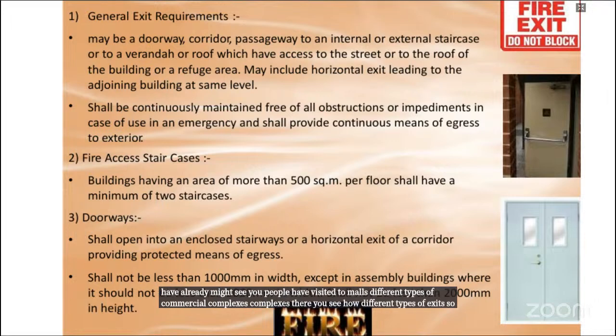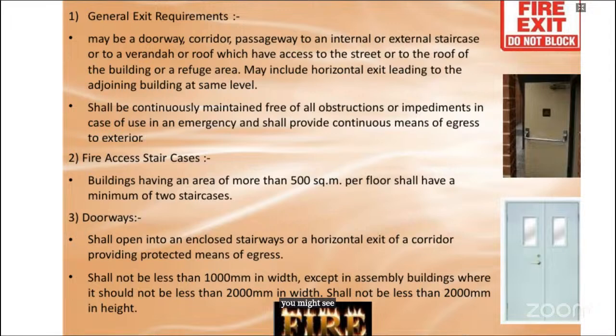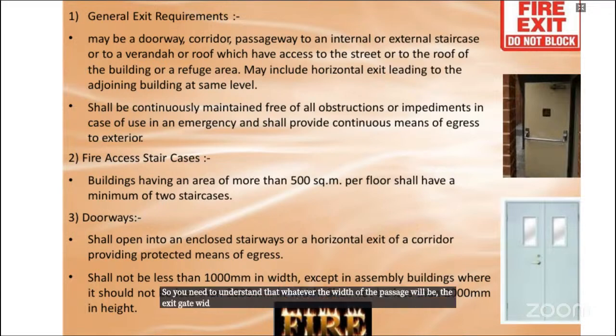You might see that the exit doors are smaller than the passage, narrowed towards the exit, which is a wrong approach towards this fire safety rule. So you need to understand that whatever the width of the passage will be, the exit gate width has to be the same. This is the basic thing which you need to understand.